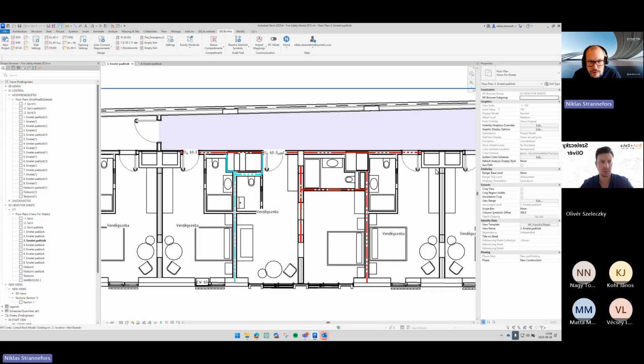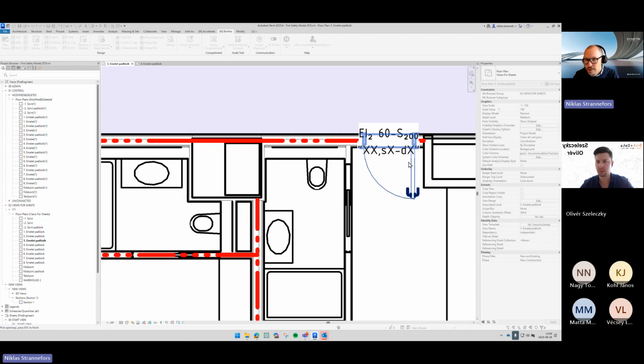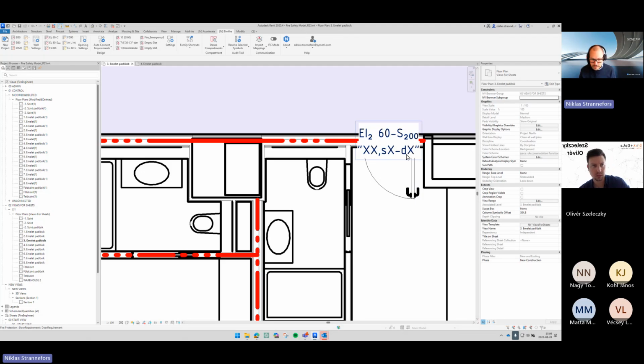Okay, so we're done basically with openings and windows. I should have changed the Norwegian thing, because this might go over your head, Oliver, but it's more a fire thing. So when you place something now, I forgot to remove it. We can remove it later. When you place something, you get the text here under, which is the material requirement on the door, because how they do it in Norway and Denmark is that they actually have the material requirement on the walls and openings. So if they're going to have the A2S1D0 requirement on the door, they're not putting it on the room itself, which I assume you guys do as well as we do in Germany, Sweden, Finland, UK. That your room decides what kind of material requirement there would be.